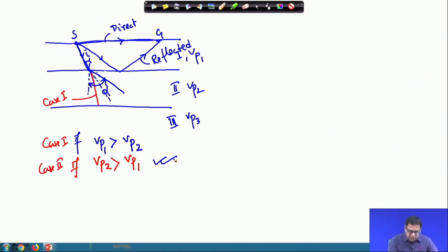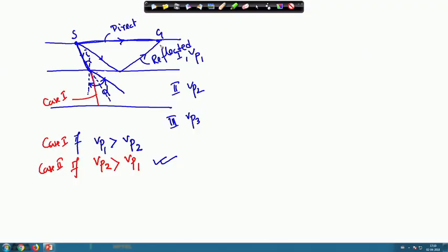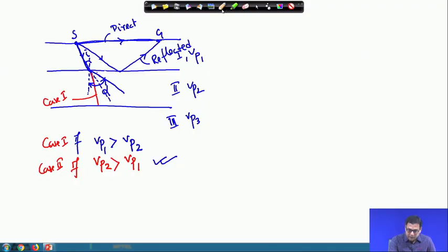So, this is important. Now, sometimes we do not have this type of layering and we will not get a good result. Then you have to go for the third option, that is the seismic cross hole survey. We will discuss the seismic cross hole survey. Now, if we are placing a geophone, there is a particular wave where, because of this angle, instead of following this path, it will follow this path.